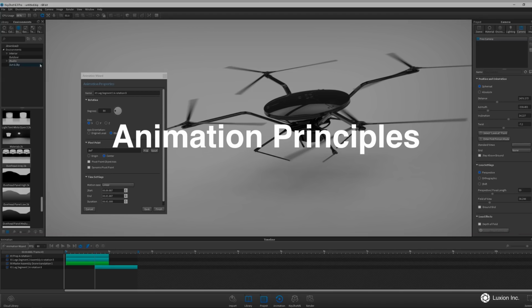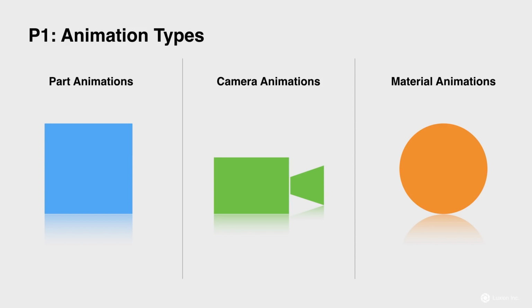Now, the animation principles are, again, as I mentioned, the items that are really going to be generic or general, all-encompassing properties or practices that you're going to want to be mindful of as you create these animations. The first of which is animation types. KeyShot has the ability to create 3 distinct types of animations at this point in time. Part animations are where you have your geometry being animated or moved around. Camera animations are those that you apply to our camera, and in KeyShot, our camera is essentially what we are viewing our scene through at any given time.